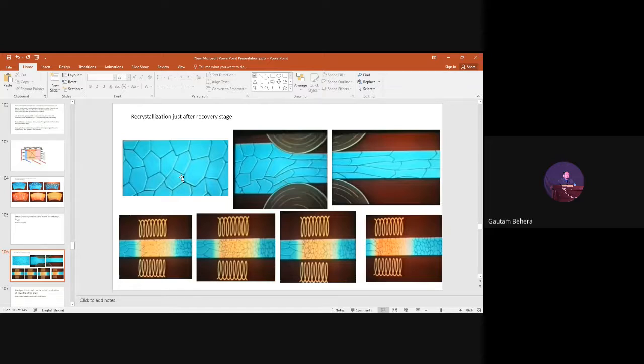That's fine, but in what conditions? How many of you have remembered? If you are not adding any kind of inoculants into the molten metal, which kind of structure will you get? And if you add? Sir, if we add any alloying element, we will get equiaxed, that is heterogeneous solidification. Very good. Not alloying element, basically inoculants, which will act as nucleating agents, as nucleation sites. Nucleation will be happening everywhere in the molten metal. That will give rise to equiaxed grain.